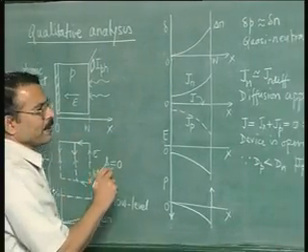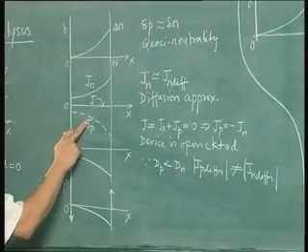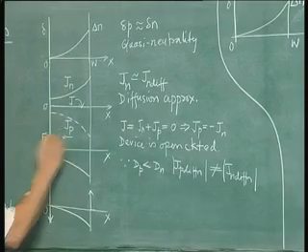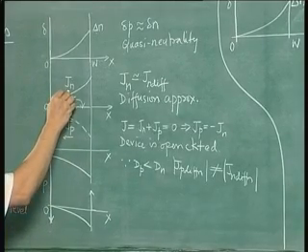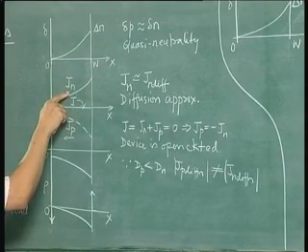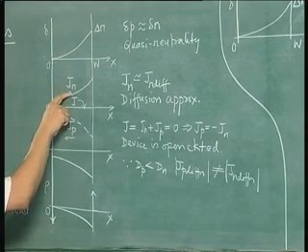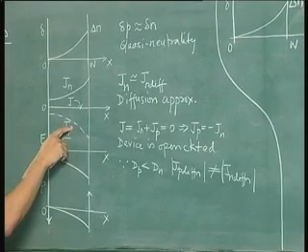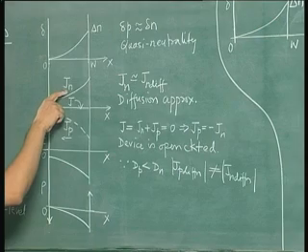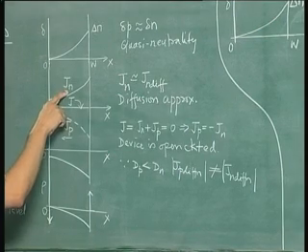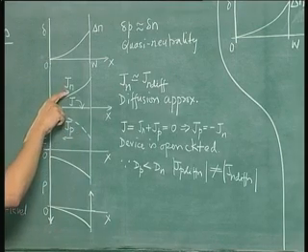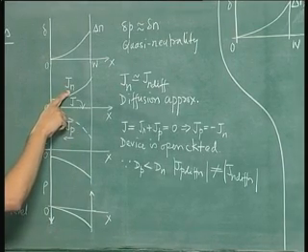So in this manner, the diffusion current of holes is aided by the electric field which is in this direction, and the movement of electrons is slightly opposed. So this is how the diffusion current of electrons is slightly reduced and the hole current is increased. In fact, the effect of electric field on electrons is small because the electron concentration is small, but the effect of electric field on hole current is large. So in effect what we can say is the electron current is almost equal to diffusion current. We will show this at the end.